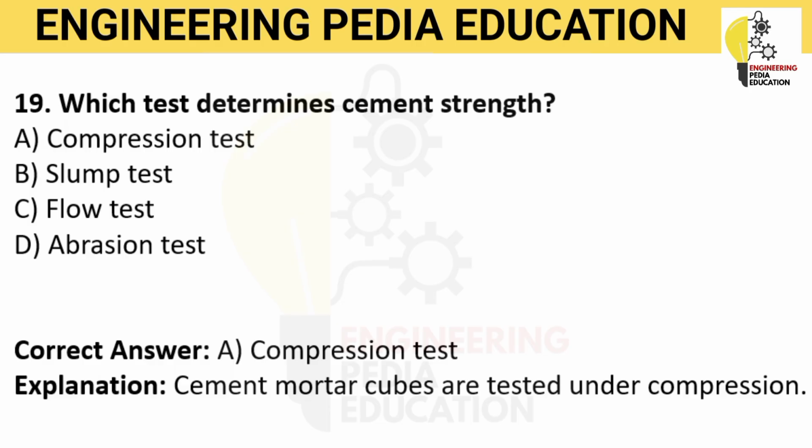Test cubes are often tested after 3 days, 7 days, and 28 days, whereas the compressive strength formula is maximum load upon loaded area.